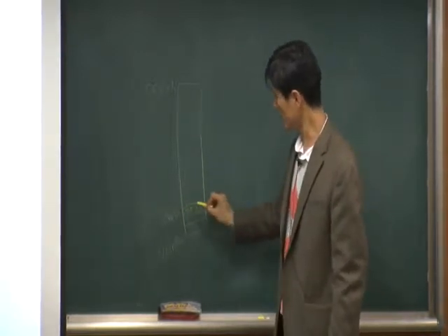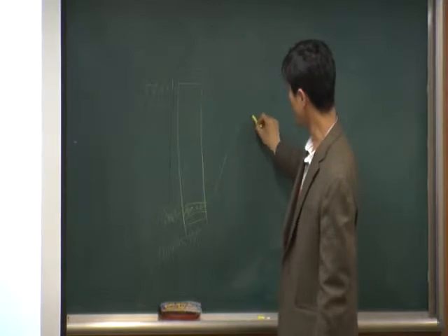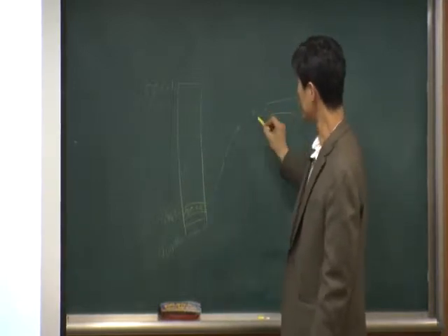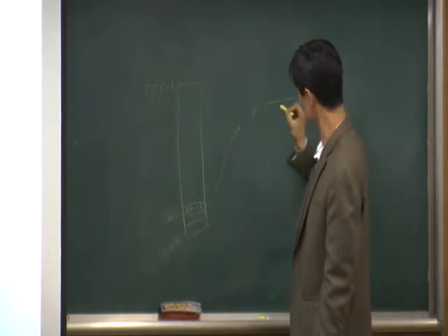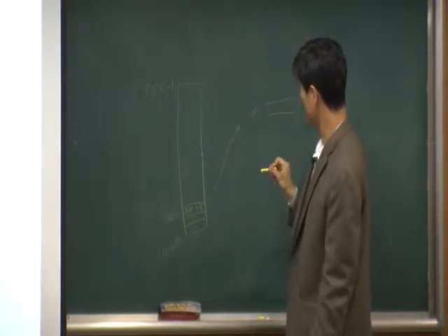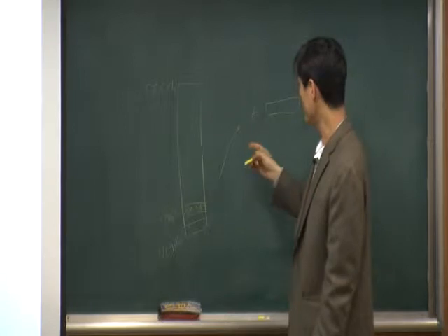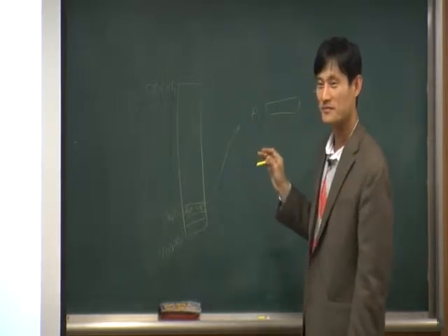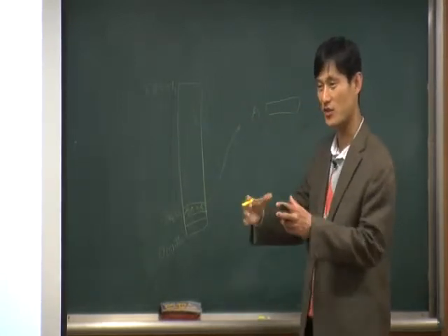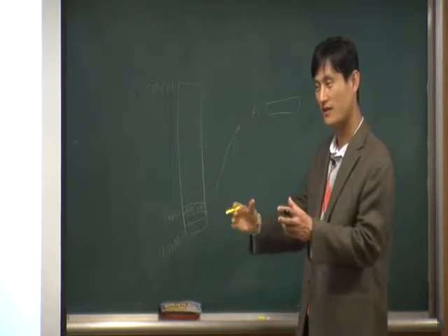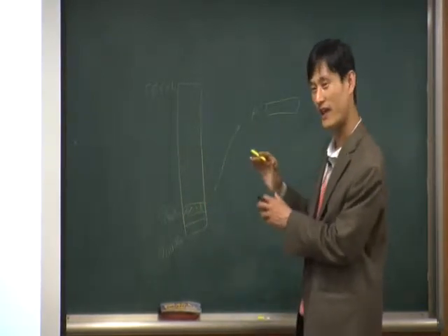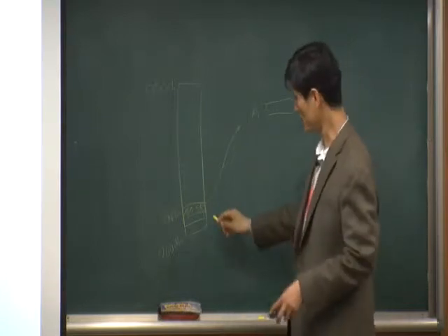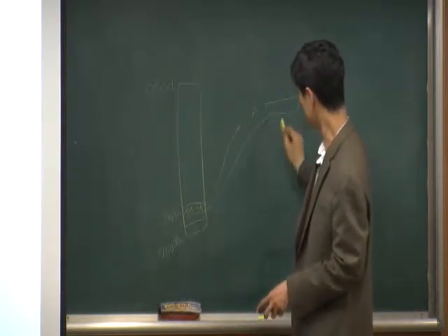So the value inside this address is now copied to A. And we don't care where A is. For registers, we are not using any address. We just say A, and you simply assume that A is somewhere. The accumulator is just a container, and that is somewhere. We don't care where it is, because we just call it A. That's it. We simply copy this value into A.